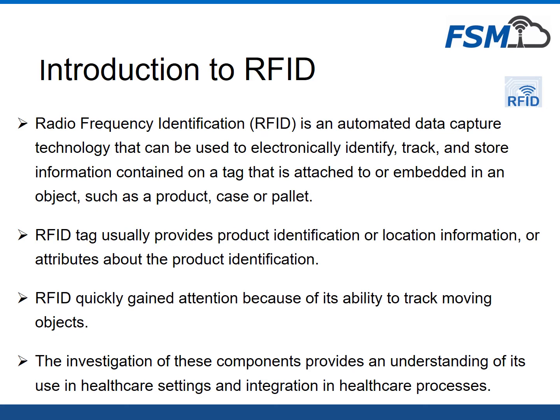The efficacy of the system depends on what form factor the tag is in. Is it paper or epoxy? Is it embedded in Teflon? Does it become part of the process? How far the reading is enhanced or attenuated with the reader in an industrial application, which form factor and which material come into play, decides what kind of RFID system we would use.